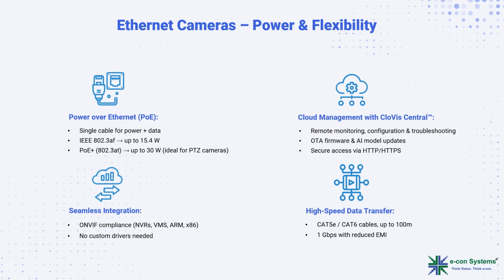Most of the cameras follow the 802.3af PoE standard, which can supply 15.4 watts of power. It's mostly enough for embedded vision cameras without any additional external power requirement. For higher power needs, we can use PoE+, which can supply 30 watts of power, which is ideal for PTZ cameras.